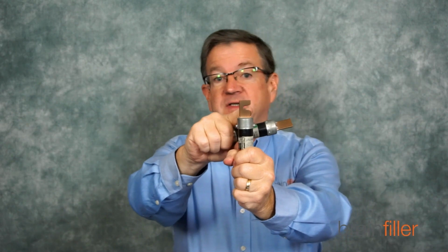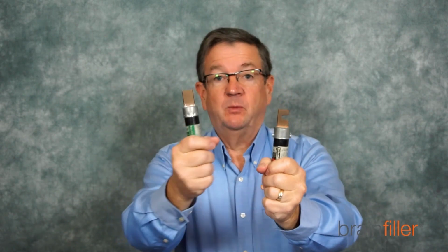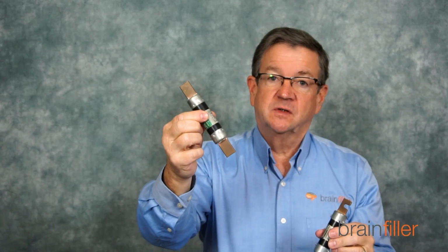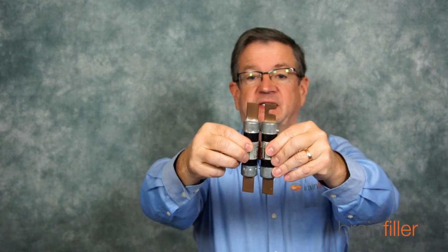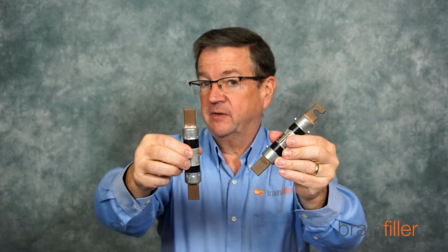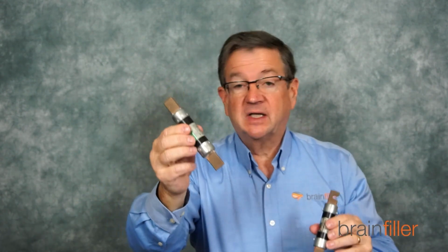And you could tell that because of the notch. And let me explain what the notch is all about. So this fuse, this is a Class H fuse. And a Class H fuse has the exact same physical dimension as the Class R, the current limiting fuse. But the difference is the Class H fuse has a much lower interrupting rating. The current limiting fuse tends to have very high interrupting ratings.